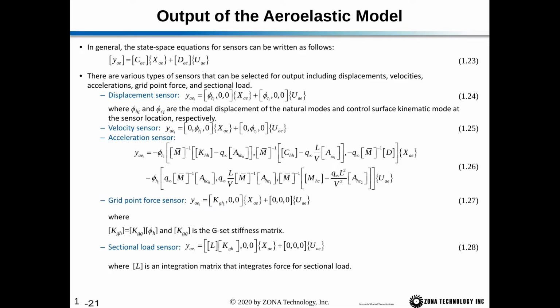Next, we have velocity sensors. So the phi and phi are instead multiplied by c dot and delta dot. And then next, the acceleration sensor. Ideally, you'd like to multiply phi times c double dot and phi by delta double dot. Now, delta double dot is available to us because it's an input. However, c double dot is not available as a state.